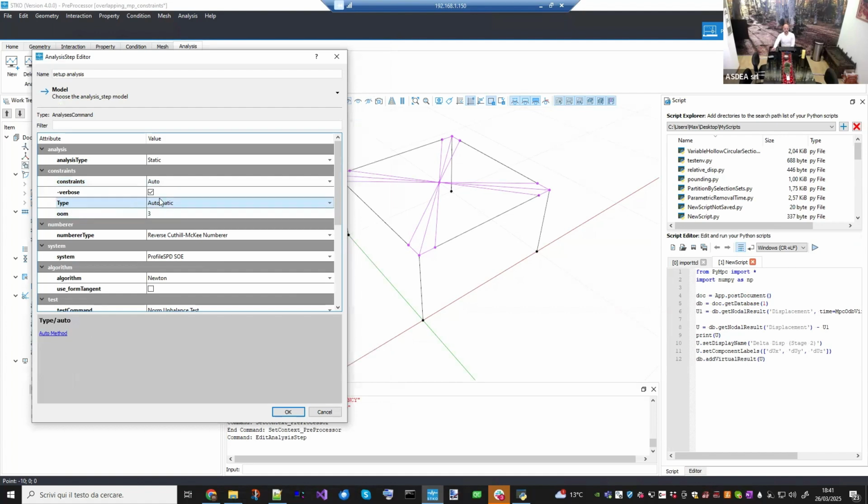So what I'm doing here is that instead of computing a user-defined penalty stiffness, I do it automatically. OpenSees will find, for each multi-point constraint, the typical stiffness in the nodes involved in that constraint, and will put a penalty value locally, which is, for example in this case, 1,000 times more, so 3 orders of magnitude more than the stiffness that is here.